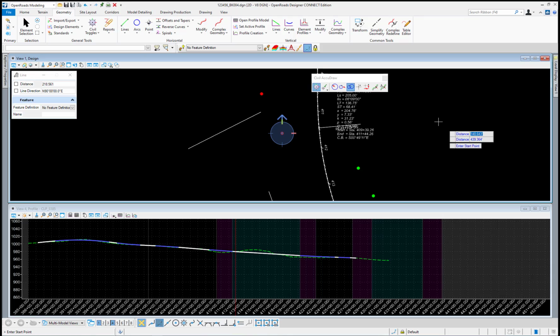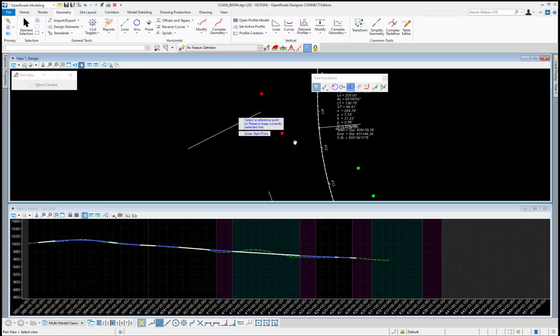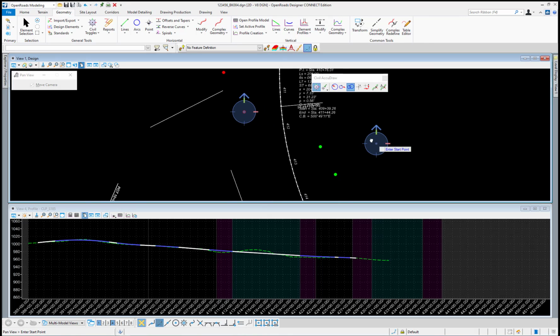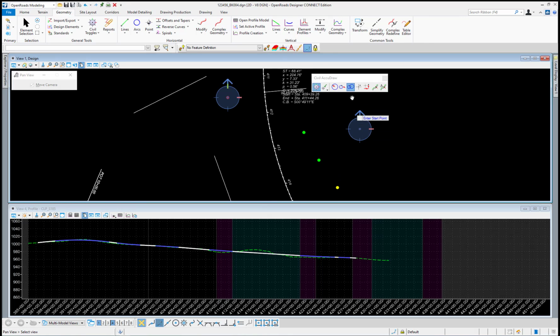Next we'll move to the distance ordinate. This will calculate a point that's two distances from two different origins. So if I want to begin a line here, notice that the first origin is trying to use the last point that we created. So to change that, I can press the O on my keyboard, and what I'm going to do is slide over and use the green points that we previously created.